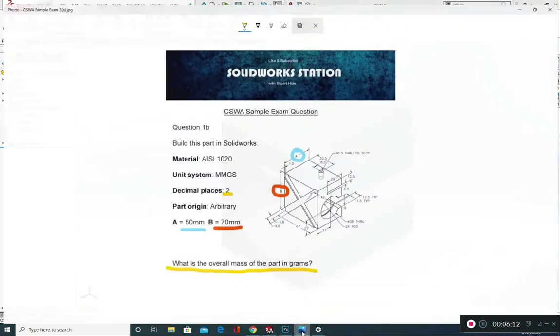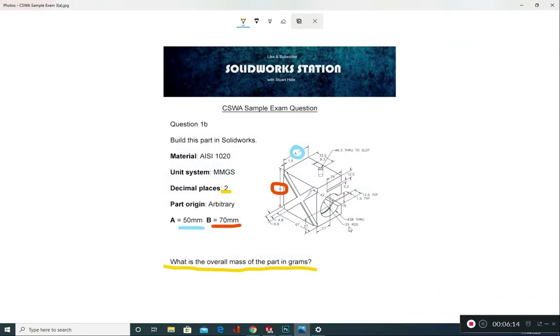Okay, the next step we're going to look at is placing in these 2x-R20 cuts. Now, because I've done this around my mid-plane, I'm going to use this value of 42 and half it to get 21 to produce this one here, which I'll eventually mirror. I'm going to produce this one first, and then I'm going to mirror it. But I'm going to half this value here to 21 when drawing in my front plane.